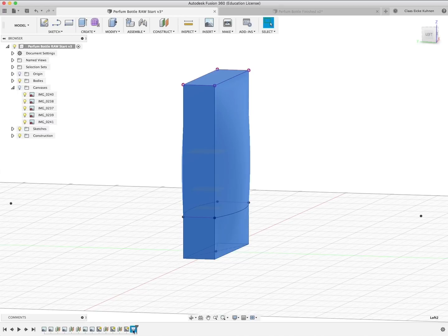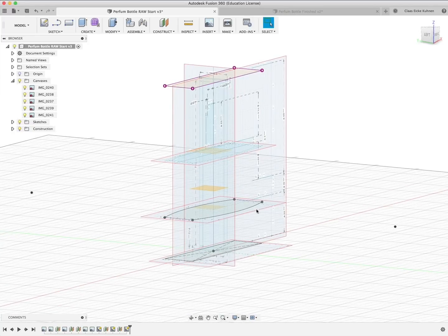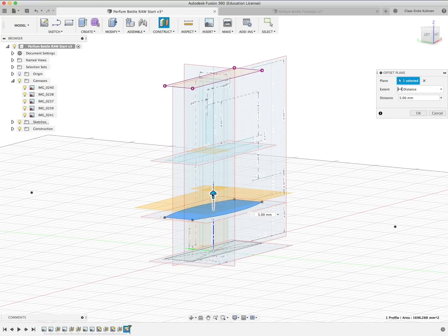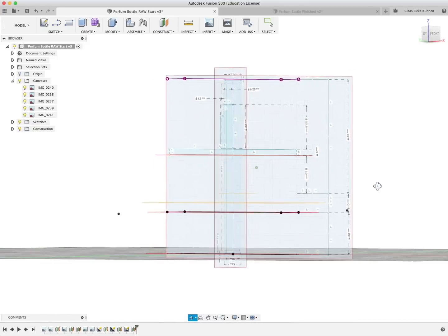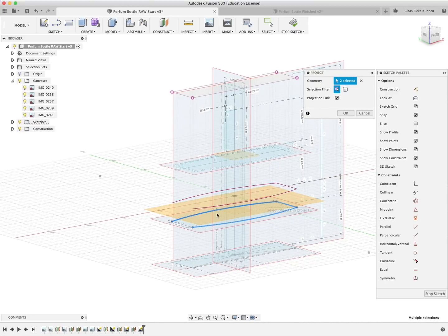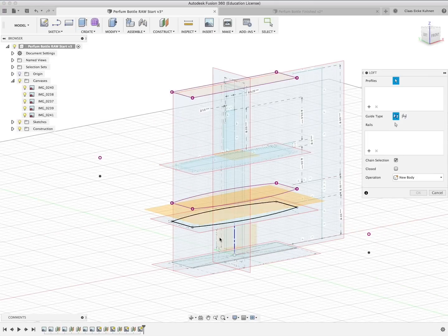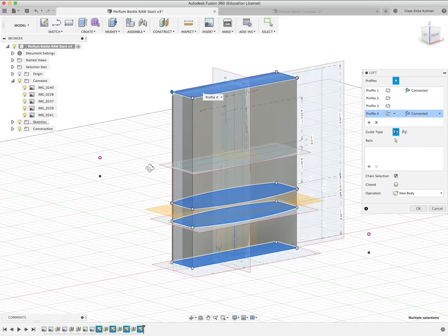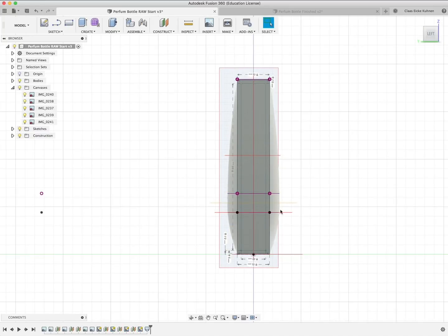In my parametric design tree, where all the different steps are recorded, I'm deleting that last command. And I have to make a copy of the sketch. To do this, again, first a construction plane. I can move this one up by exactly 10 millimeters in my case. Then another sketch right there, and inside the sketch I can project the previous sketch I made. Now if I do the loft again, from there to there, you can see how we rerouted that flow quite nicely.